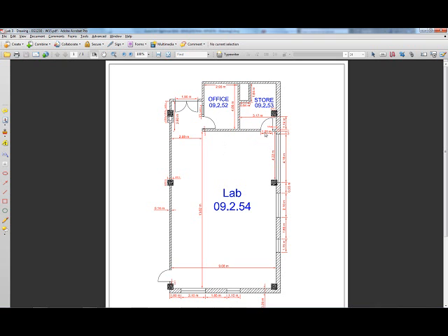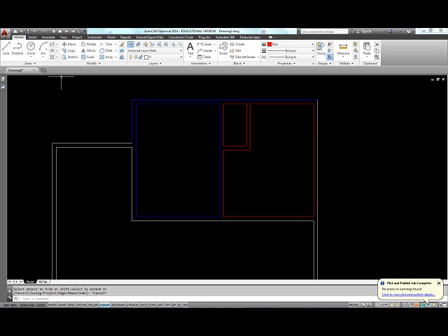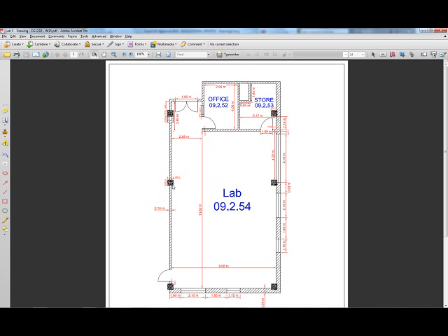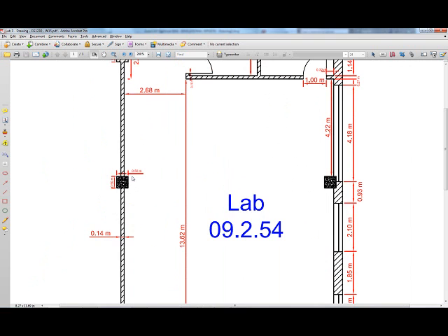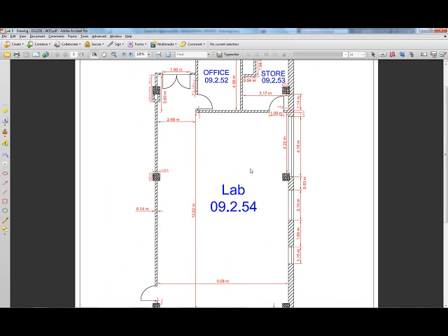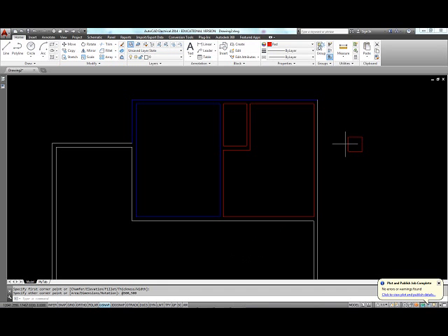We can now create these columns. So I can say again, the rectangle, go anywhere, and then at 500 comma 500. Why? Because the dimensions here tell me it's 50 centimeters by 50 centimeters, and I have 6 of them. 1, 2, 3, 4, 5, and 6.